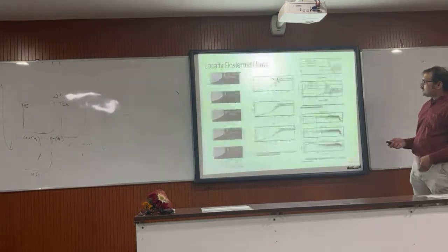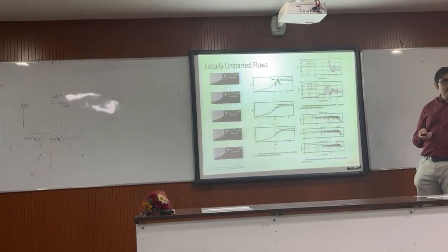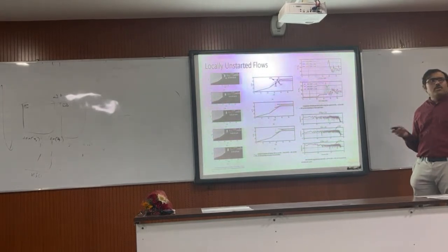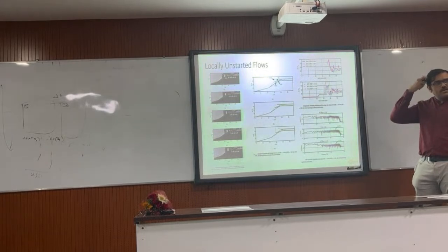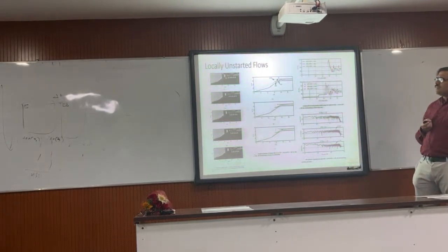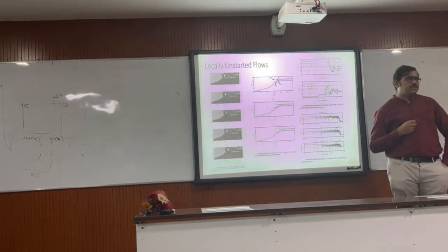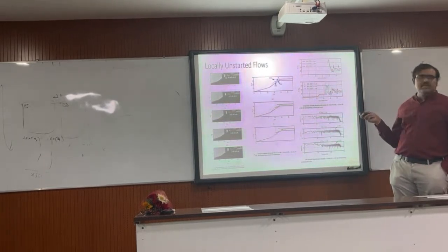Here we used an unsteady simulation with the SU2 software and the SA turbulence model, with compressibility correction and so on. Time steps were in the range of 10 to the power minus 8 to minus 7. It took quite a long time. One particular simulation took something like one or two weeks, and this is only for 2D. Our time step is small, and we had to look for stability, and these oscillations were captured.